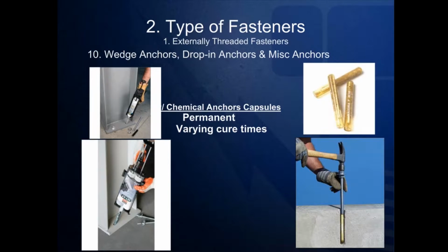Of course, all of these first start with a hole being drilled by an SDS drill bit. Epoxy cartridges come in a variety of types of dispensing methods. Some will fit with a standard yet heavy-duty caulk gun, where other brands would require an expensive double-chamber gun. Chemical anchor capsules are also another way that epoxies are installed, in which the user drops a test tube-looking capsule into a hole. The tube is then broken when a piece of threaded rod or rebar is hammered into the hole, thus mixing the epoxy together.